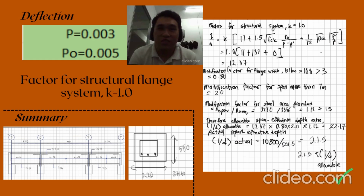So as you can see, the factor for the structural system K is equal to 1.0, and as you can see, my LD allowable is more than my LD actual, therefore the condition is okay. And on the left, you can see the summary drawing from beam 1 to F, and that's all from me for the simply supported beam.